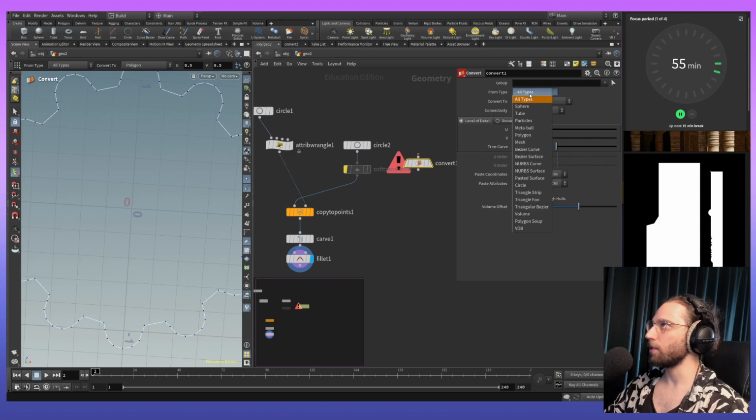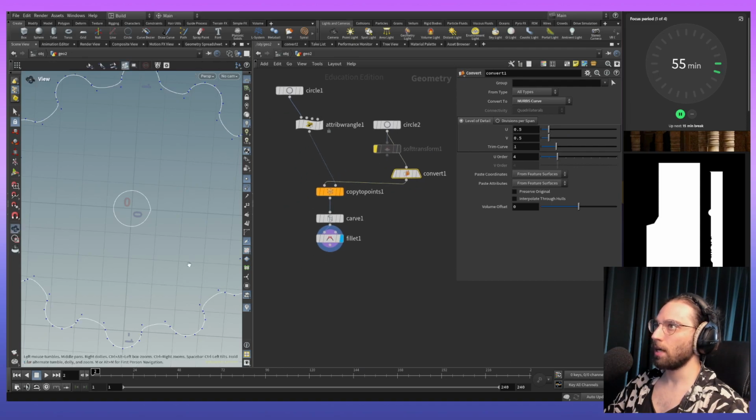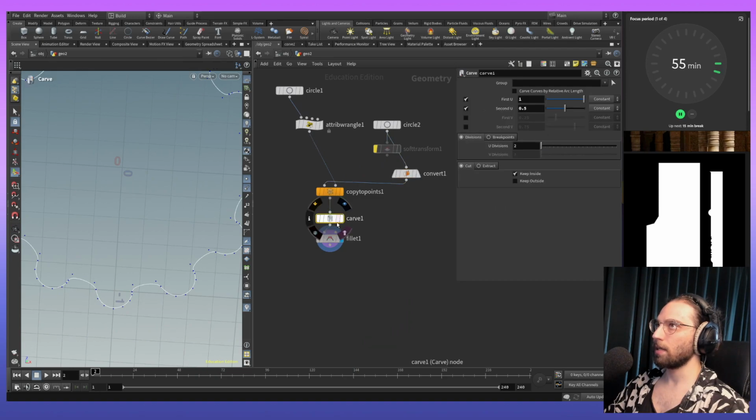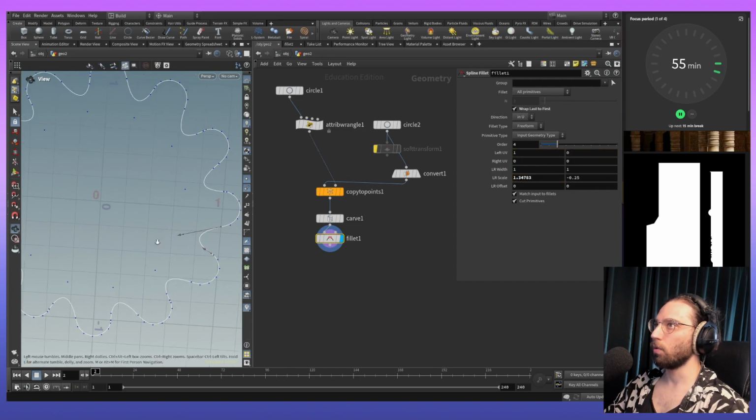Of course, it's not a religion, but just for me to understand things and learn things faster, we will use the convert node to convert this thing into a NURBS curve, like right there. Okay, so we will put it right there and hook it now to the actual copy input. And you could see now that the fillet here has different values. And it already switched actually. And now we could play with this a bit more freely, and it will give us cooler shapes to work with.